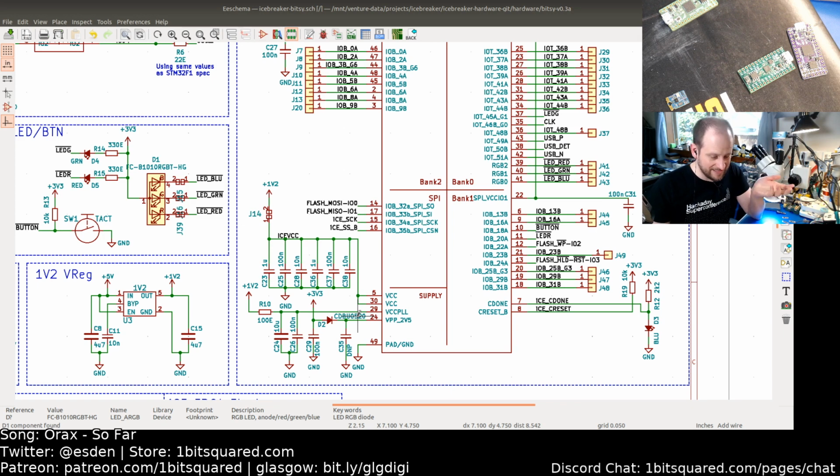So someone at Lattice, when they designed the PCB, thought, oh, I can just add a Zener diode to drop from the 3.3 volts down to 2.5 volts and use that as a supply for the NVCM when you are trying to program it. But it turns out that this cannot provide enough current, and it just drops the voltage too fast, and this doesn't work.